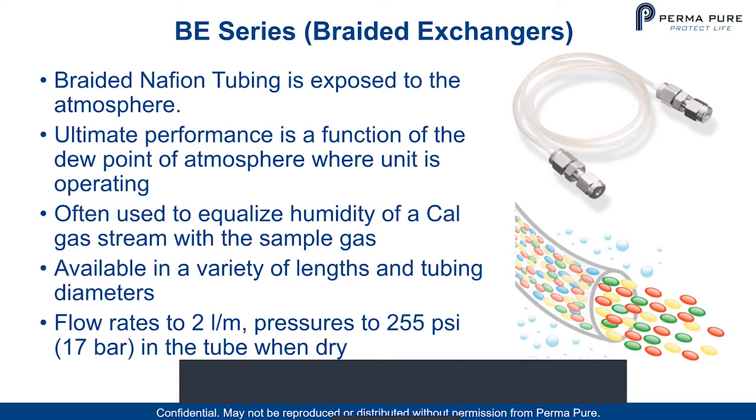What we do is we injection mold a polypropylene end in various types of sizes and shapes and connector designs. But basically the concept is that we are encapsulating the polypropylene netting. And that provides a very strong strain relief, where we provide a plastic attachment where we can attach a connector, as shown on the picture there at the right.